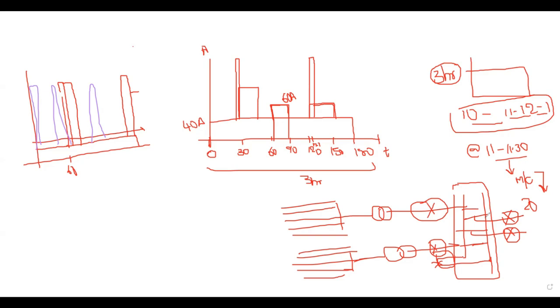In that condition, with failure of the DC, failure of the battery and failure of the AC, in that period the operation of the double busbar 2 times, 3 times is highly unlikely. I cannot say it's impossible. It can be, but the probability is very, very low. So just think in that context, and you have to prepare your own duty cycle for this.